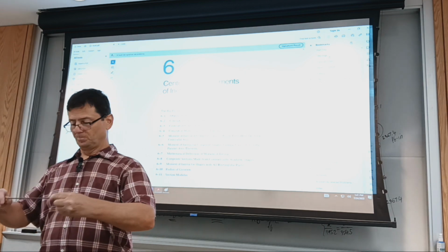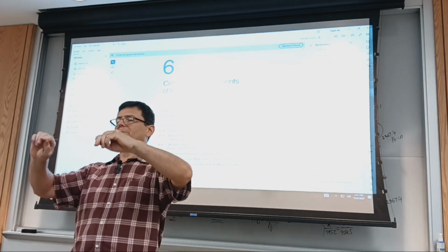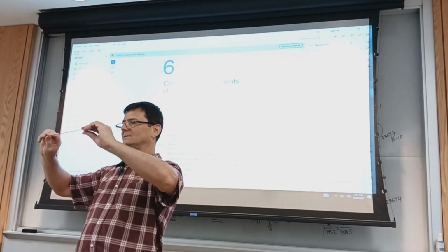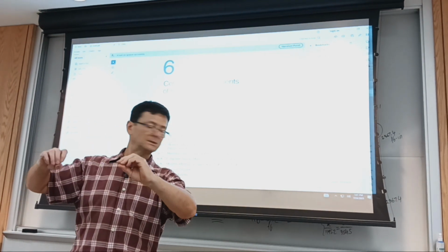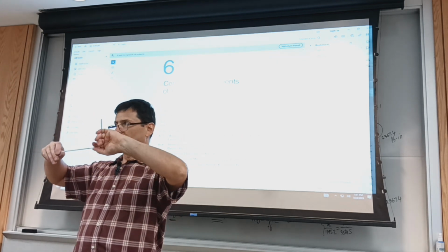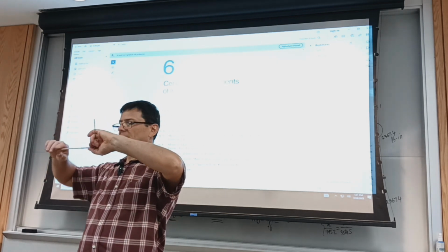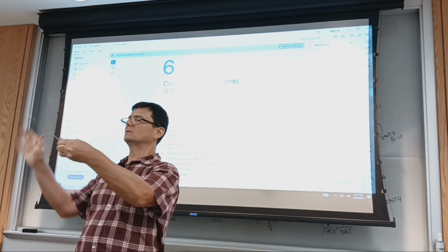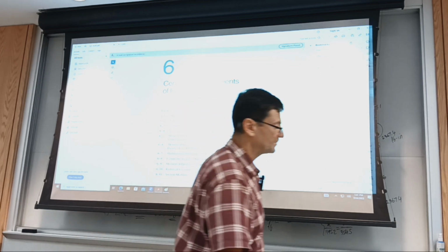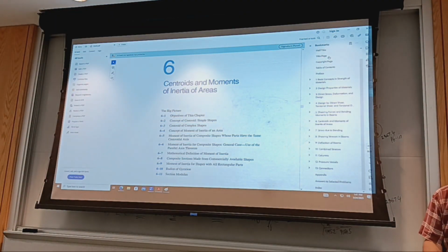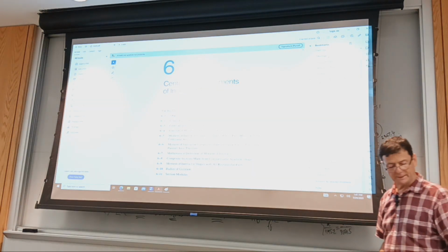When it comes to resistance to bending, if I bend this flat, with a force in the middle, it's one thing, but if I rotate the section 90 degrees, it's much stiffer. I'll not be able to easily bend it. I could right away bend it if I load it on the flat surface. So that's why we study area properties.